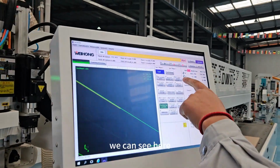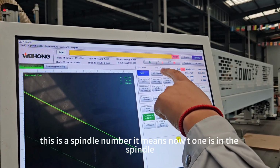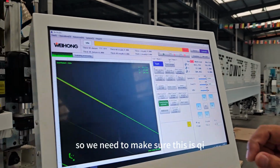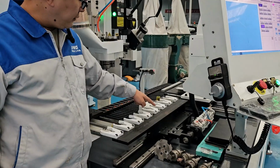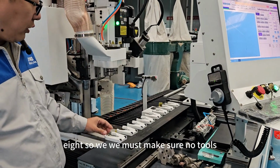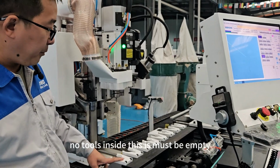And then we can see here, this is the spindle number. It means now T1 is in the spindle. So we need to make sure this is T1. 1, 2, 3, 4, 5, 6, 7, 8. So we must make sure no tools inside. This must be empty.